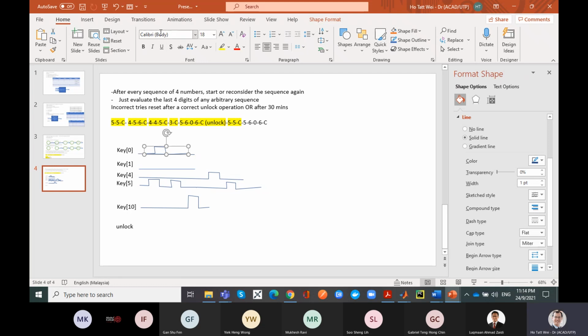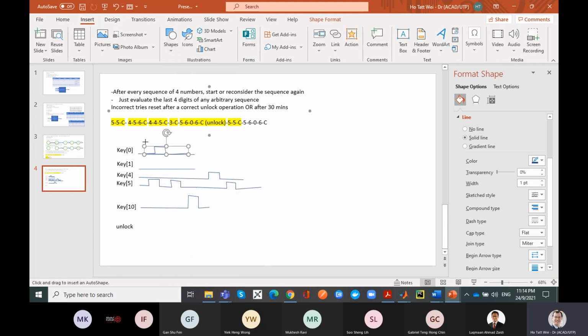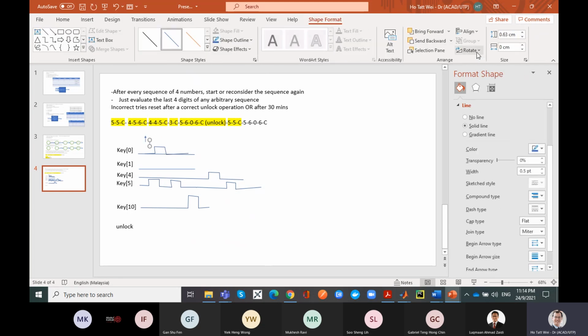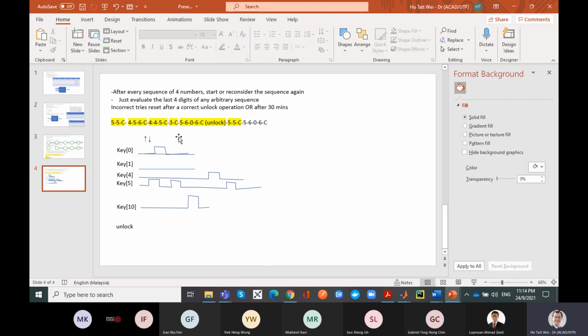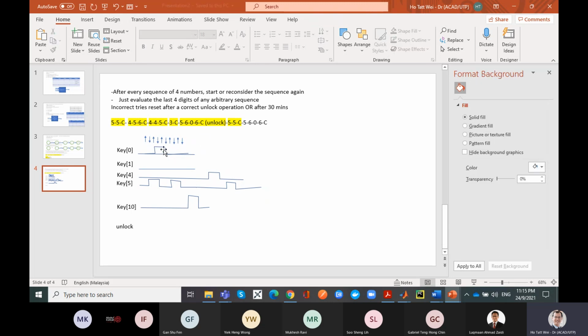And one way people have worked around this is they don't take pure combinational like that. They define a clock signal. Okay, so now I'm going to draw a clock signal in a different way because I'm a bit tired of drawing it the whole way. I'm just going to draw up and down arrows so you know that this is the clock edge. Okay, you can follow. So you define up and down signals in such a way that you only allow yourself to update inputs on these up and down signals, right?